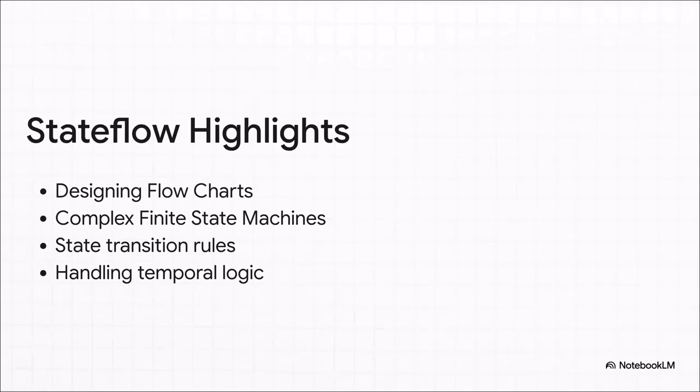You're going to learn how to achieve 100% structural coverage, including strict MCDC metrics. MCDC stands for Modified Condition/Decision Coverage, and it's basically a very rigorous way of mathematically proving that every single logical switch in your design has been tested independently. Literally, no stone is left unturned.